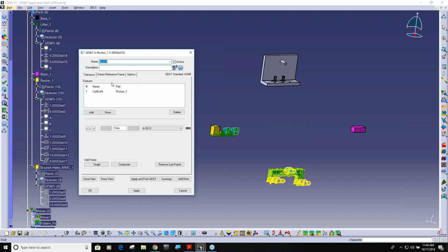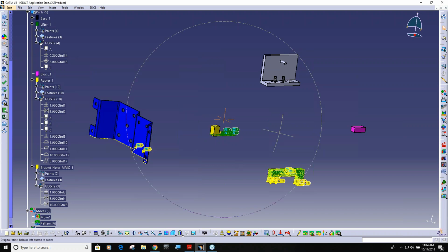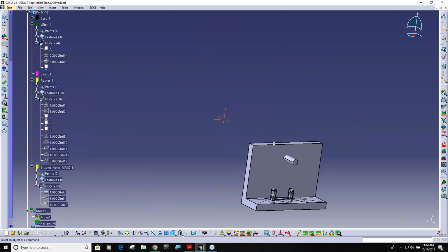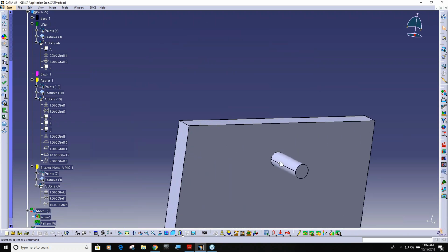So within a CAD system, the way that it works is that you have to define datum A and then define perpendicularity back to A. Then you have to go ahead and create your datum B on that perpendicularity. So it's just something that I realized is that you are not necessarily required to follow that same order.